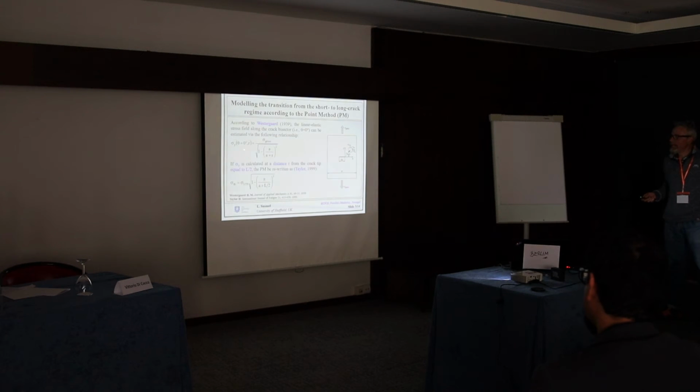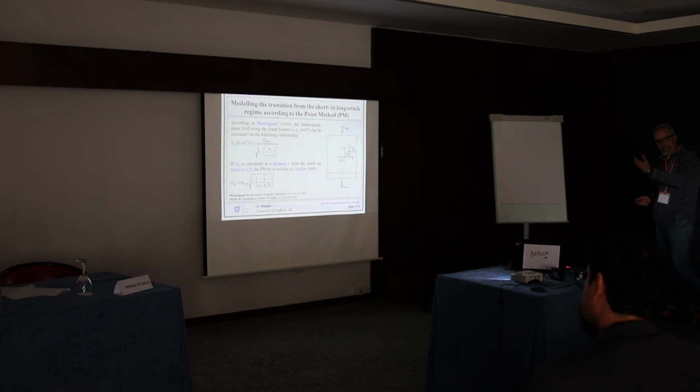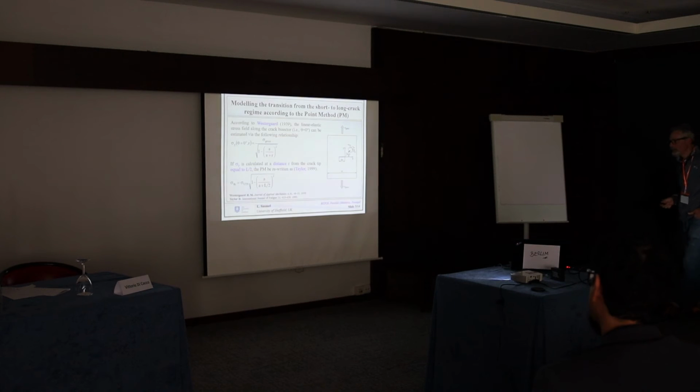So you can then use the TCD, the point method, together with this stress distribution, and you can have a nice formula which gives you the failure stress based on the combined use of Westergaard's solution and the point method. And this nice simple formula was derived by my friend and colleague David Taylor back at the end of the 90s.